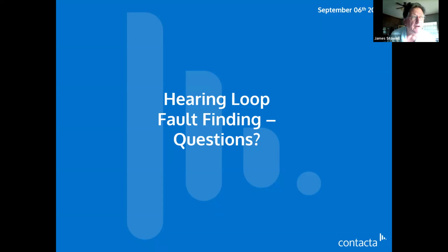So, Dave, one of the things I didn't see covered in here today is that you could lay your perfect loop, phase array, everything is great. When you plug the V22 into the wall socket in the church, you get two red crosses immediately. Unplug it, they go away. The fault error is in the building, not in your loop and not in your driver.